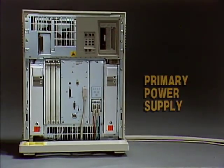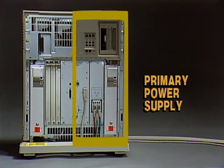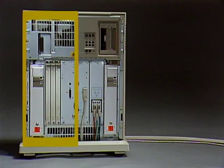The right power supply is the primary power supply. It provides power to the right half of the box, slots 1 through 6, and to the two rightmost mass storage cavities. The left power supply provides power to the left half of the box, slots numbered 7 through 12, and to the two leftmost mass storage cavities.